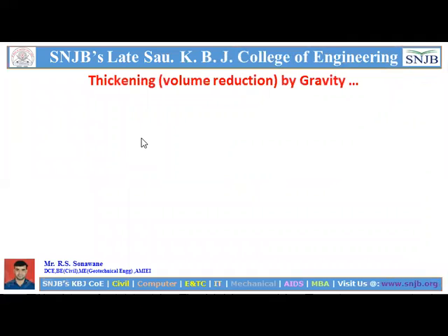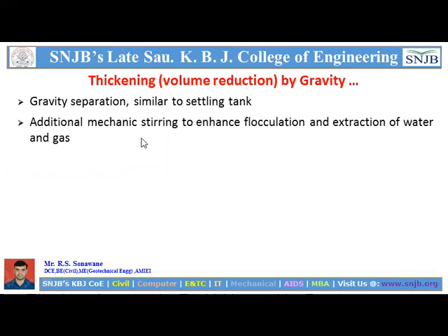Now thickening. What exactly is the meaning of thickening? Volume reduction by gravity is called thickening. So it is gravity separation, similar to a settling tank. Additional mechanisms, such as stirring, are used to enhance flocculation and the extraction of water and gas.